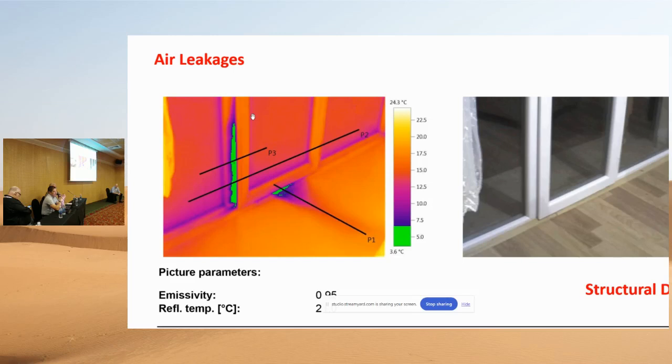I don't think that's the price for the whole building complex, like a residential skyscraper. That's a different story. You will not do the blower door test with simply one framing door, but maybe a multi-framing door, or in some skyscrapers there will be one truck coming with a huge blower or fan, and that will be a different budget. But for single-family houses, the budget that you pay for the blower door service will not even cover one window.